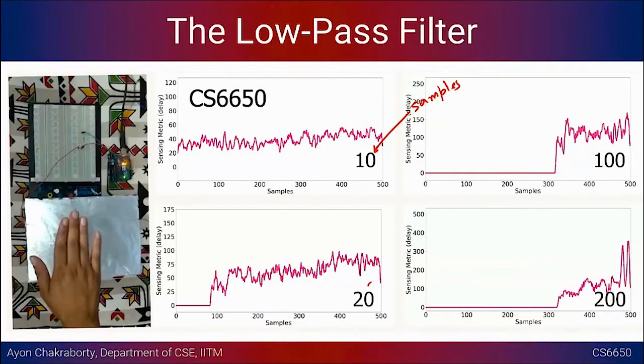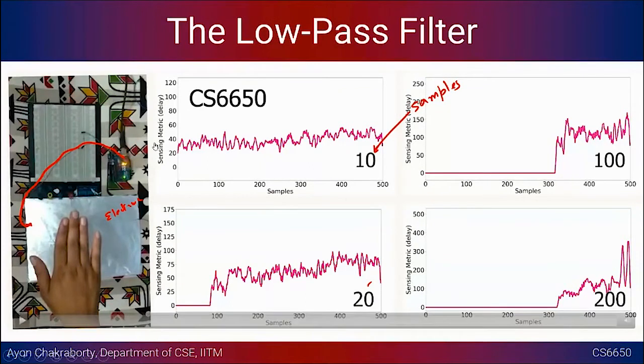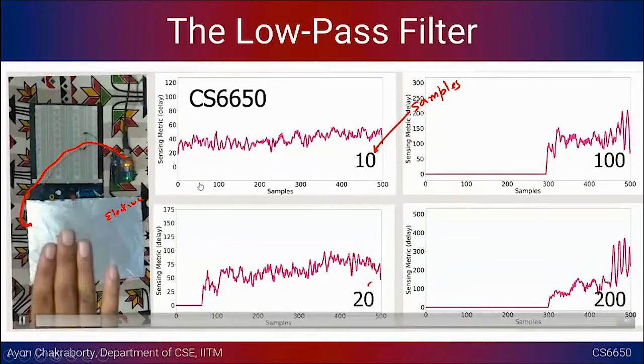What we are doing here is, you have the simple sensing circuit implemented on this breadboard, and on the right hand side we have the Arduino, and you are seeing what is being sent out from the Arduino to the PC. This is the output, the serial output, and this is our electrode. We have a small wire connected here, which goes all the way to the sensing pin. What I am doing with my hand is not always touching it, but trying to make some movements without touching the electrode. So this is more of a proximity sensing.